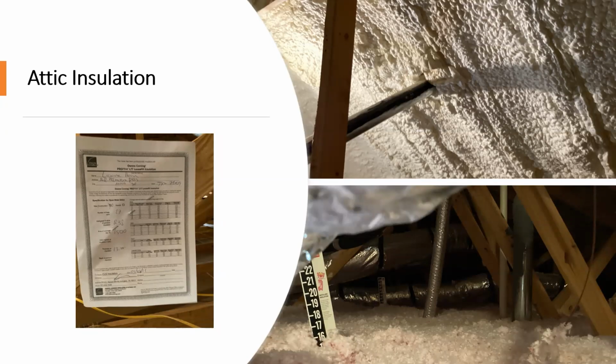It determines what the R value per inch is, what material was used, what depth I should be seeing in each cavity. And then, of course, traditionally, you'll see a certificate in the attic showing the attic insulation being blown, number of bags, what the coverage is on each of those bags per square foot. All that being done needs to be posted. That's moving the liability to the installer, saying that he did his job correctly. And so when you're doing your inspection, you're looking at it and saying, yes, it's correct, or I have questions whether it's correct, the liability falls on the installer.